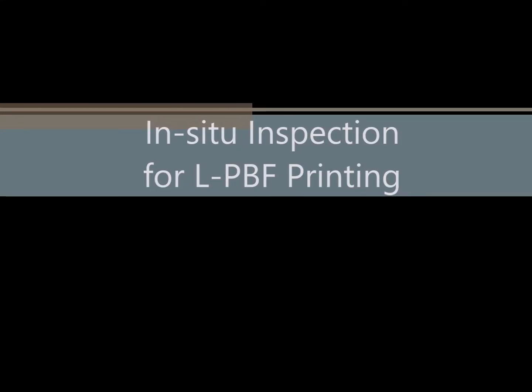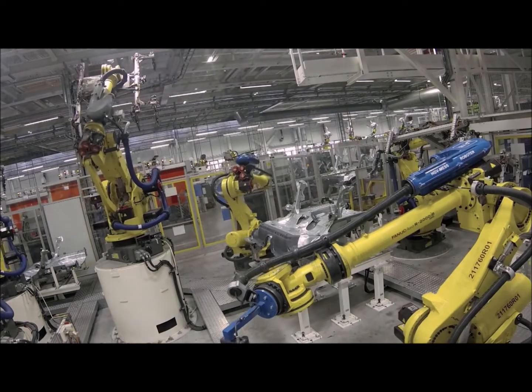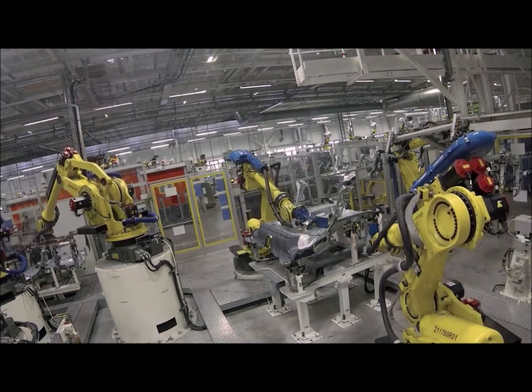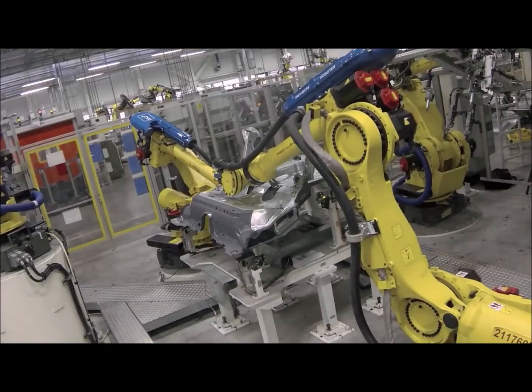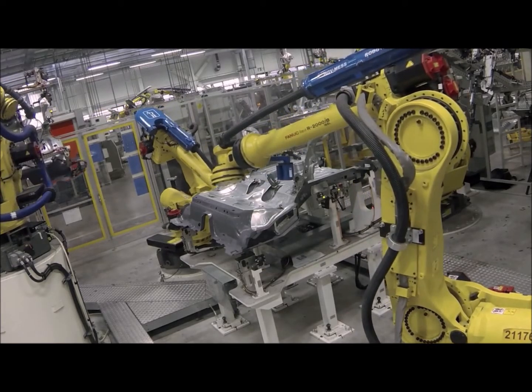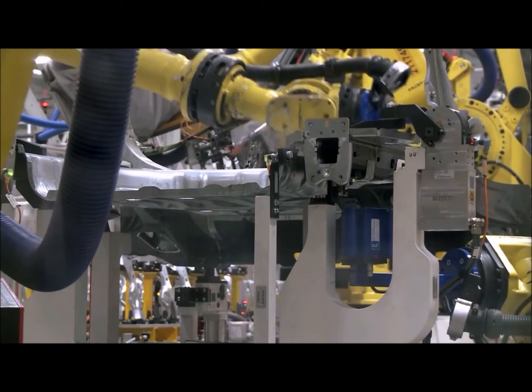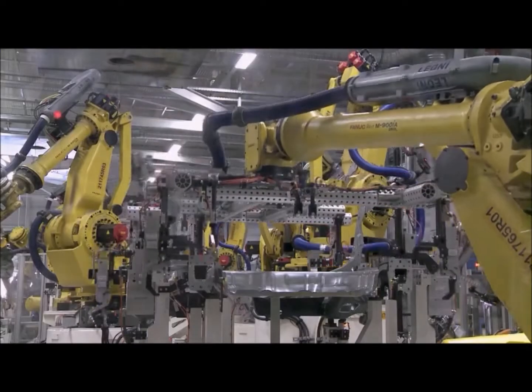In-process inspection has been widely used for many years in many different industries because of its proven benefits. Modern manufacturing, whether automated or manual, actively measures product quality throughout the process to understand process variation. Using methods like statistical process control, or SPC, the earlier flaws or defects are detected, the lower the cost to identify and correct the problem.